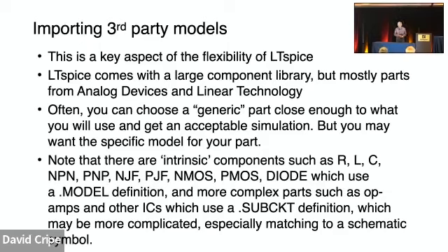The intrinsic devices are the easy ones, like NPN, PNP, JFET, positive and negative, NMOS, PMOS, and diode. For one thing, they all match the internal symbol. Now, more complex ICs use a sub-circuit definition, and one thing that makes it more complex is their package. You've got to have a symbol, and its pin numbers have got to match up right. But we're just going to talk about a common op amp. Well, the first thing we're going to talk about is a transistor. That's easier.